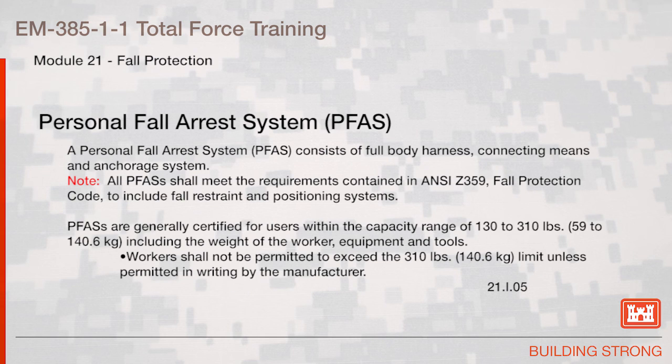Personal fall arrest system. A personal fall arrest system, or PFAS, consists of a full body harness, connecting means, and an anchorage system. Note, all personal fall arrest systems shall meet the requirements contained in ANSI Z359 Fall Protection Code to include fall restraint and positioning systems.